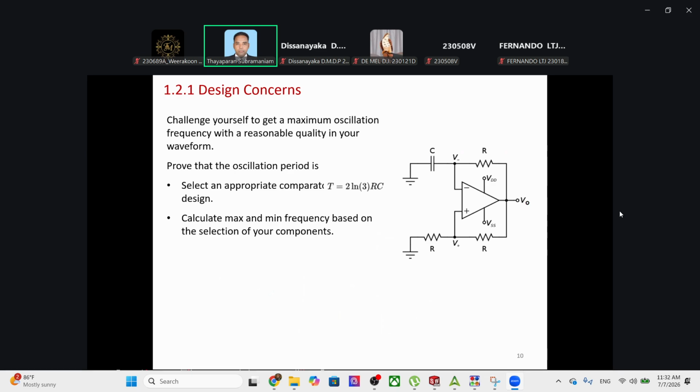Is it the resistor tolerance, or the selection of value, or the op-amp input current ratings, or the selection of supply voltage? Which one brings the maximum deviation or maximum error in the output, to put it in simple terms? So we target that particular parameter, which brings the maximum. We cannot simply go and ask, otherwise we don't know what to do.